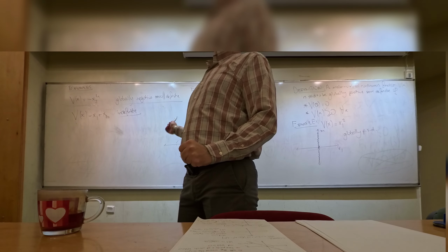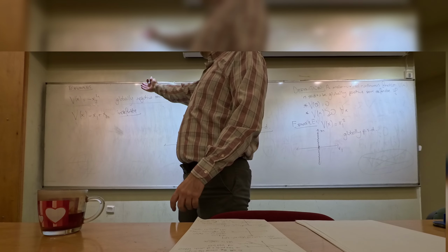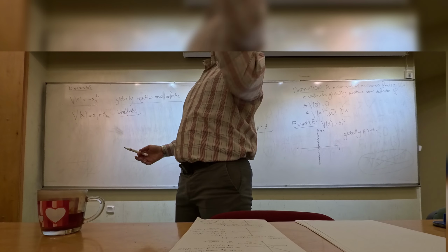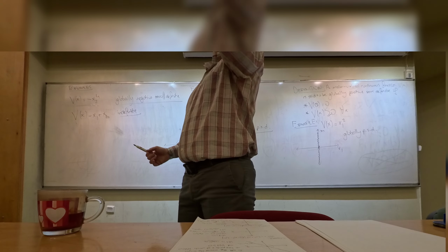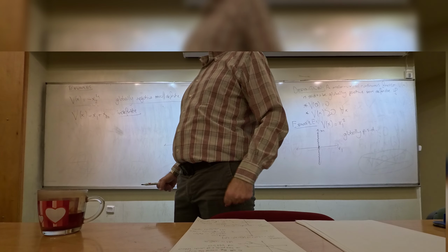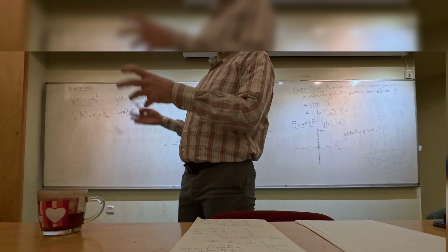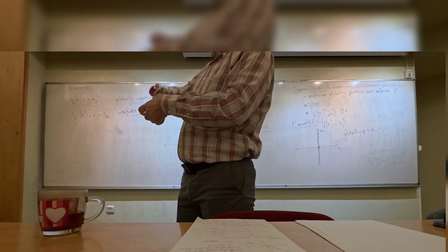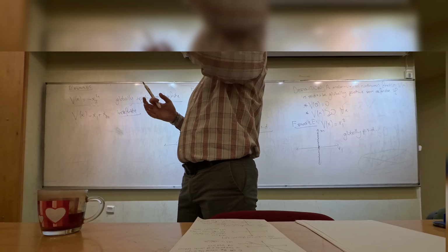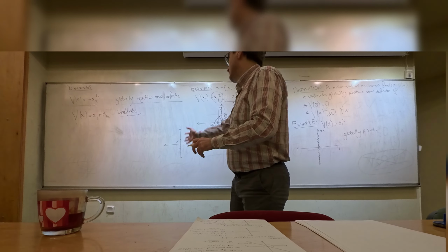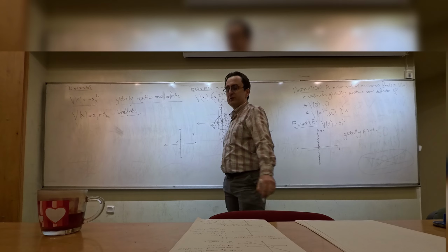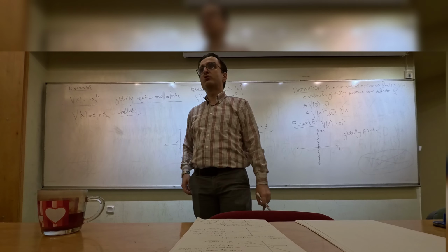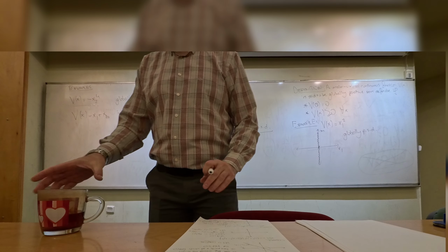In general, these functions are defined at the origin. But if the equilibrium point is somewhere else, then you have to define those balls around the equilibrium point. Because we can always define a new state variable that would pull the state to the origin, definitions around the origin will be sufficient. But if you have an equilibrium point somewhere other than the origin, the function has to be defined around that center.